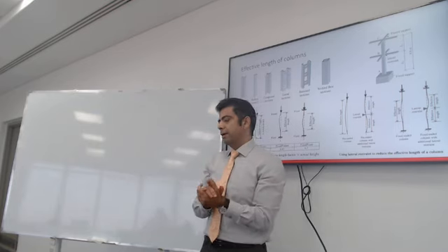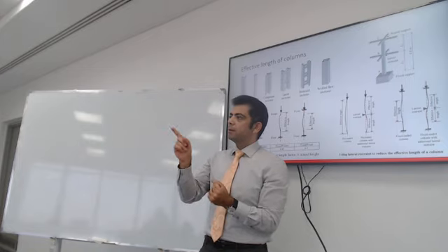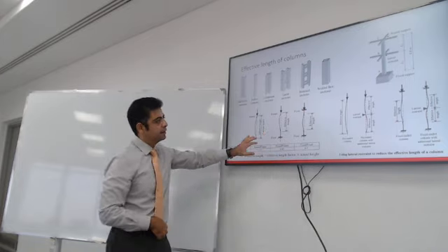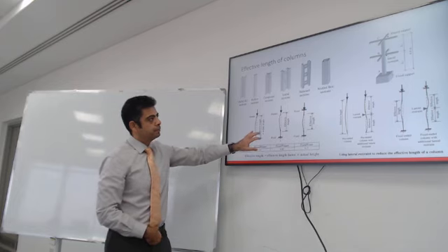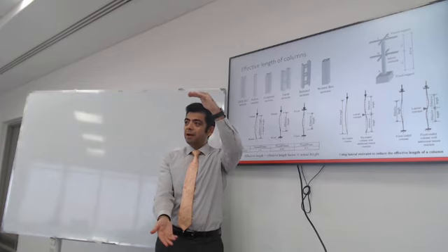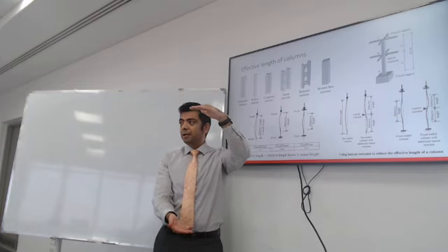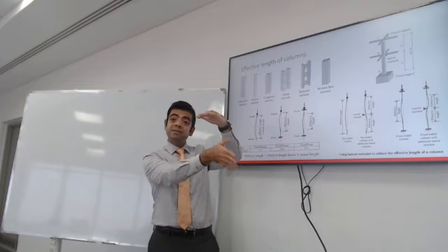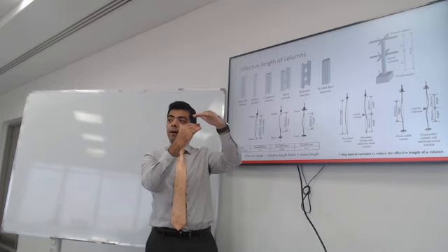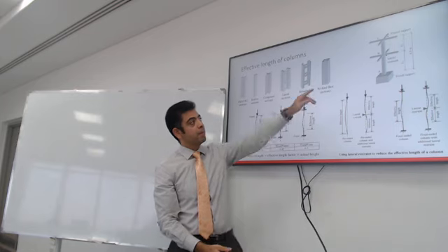So here's what I want to say. There is another very important factor before we spend too much time on this. The height of a column in a building like this could be braced by another beam at mid-height or along its length. It would be something like this.